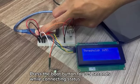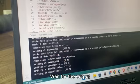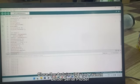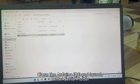Press the boot button while connecting status and we will wait for the output. The output will display time elapsed, threshold value and also raw value. Press the Arduino and launch Beta Serial Plotter and then choose the correct port and baud rate. Click plot all data and zoom out until you see all the data signal. Adjust the threshold value until it is above raw value.